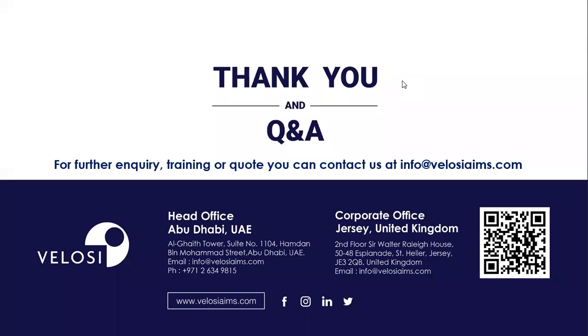Next question. How to test the SIF initiator, logic solver, and final element and send to Exida for certification? See, there's no third-party certification, like if any SIF has to be tested. The SIFs are installed at the plant. There's not one SIF, there's a complete ESD system and ESD loops. And these SIFs can be tested during startup, shutdown. In between, their testing is difficult, right?